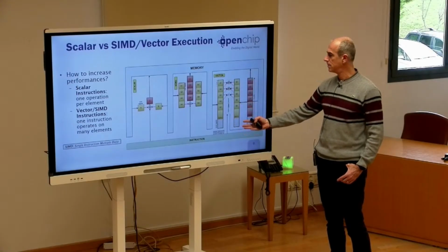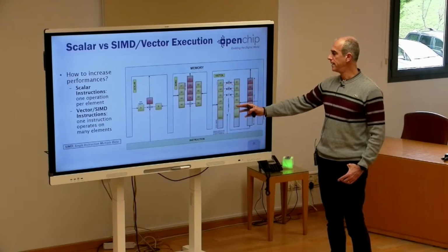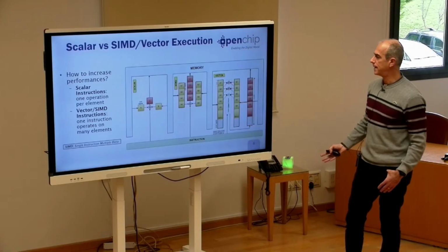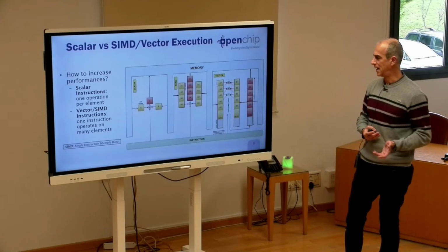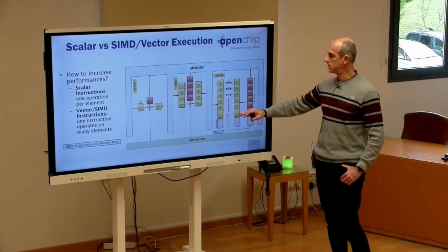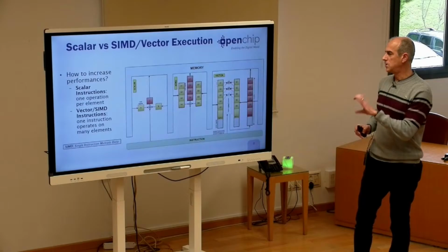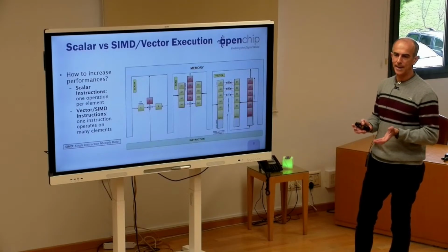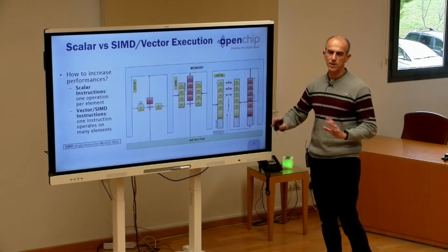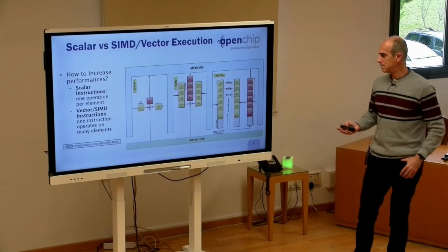It is very flexible, and because you can decide also how many computing units you can put here, you have the flexibility to decide how many units you will put here, and so create a more powerful or a less powerful hardware. And then comes also the concept of lanes, because you can think to divide this big vector in pieces and put each piece in one structure, which is called lane, which can do the computation. And if you want to increase the number of data, you just increase the number of lanes, and you can extend this hardware as much as you can.